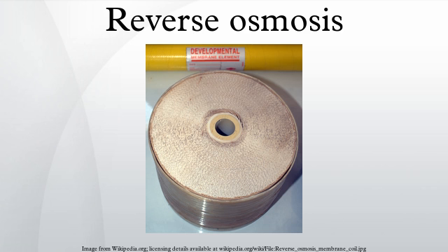The process is similar to other membrane technology applications. However, key differences are found between reverse osmosis and filtration. The predominant removal mechanism in membrane filtration is straining, or size exclusion, so the process can theoretically achieve perfect exclusion of particles regardless of operational parameters such as effluent pressure and concentration. Moreover, reverse osmosis involves a diffusive mechanism, so that separation efficiency is dependent on solute concentration, pressure, and water flux